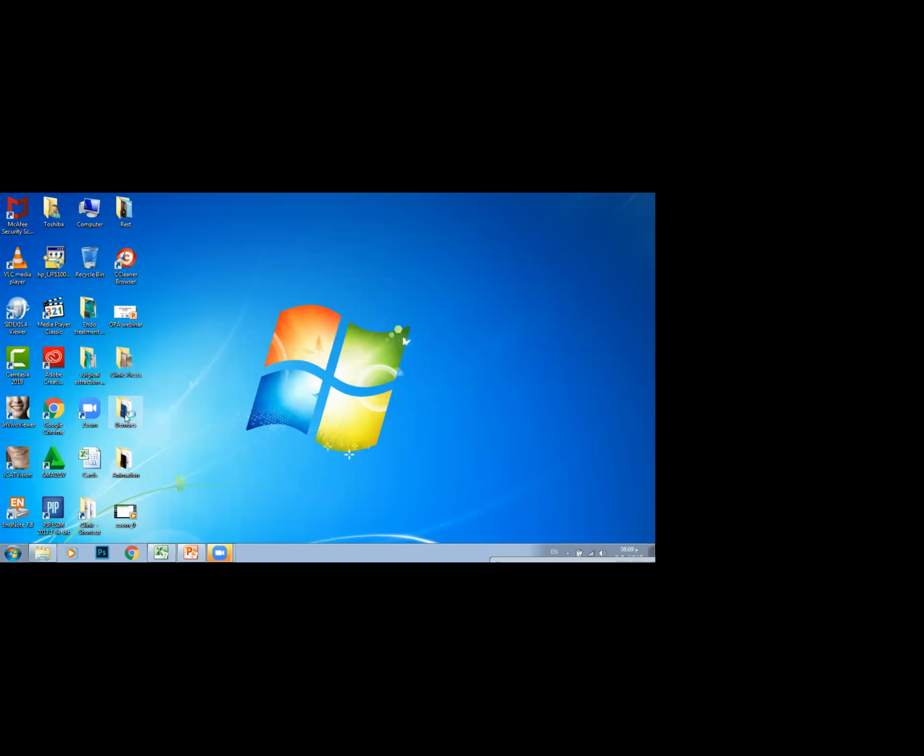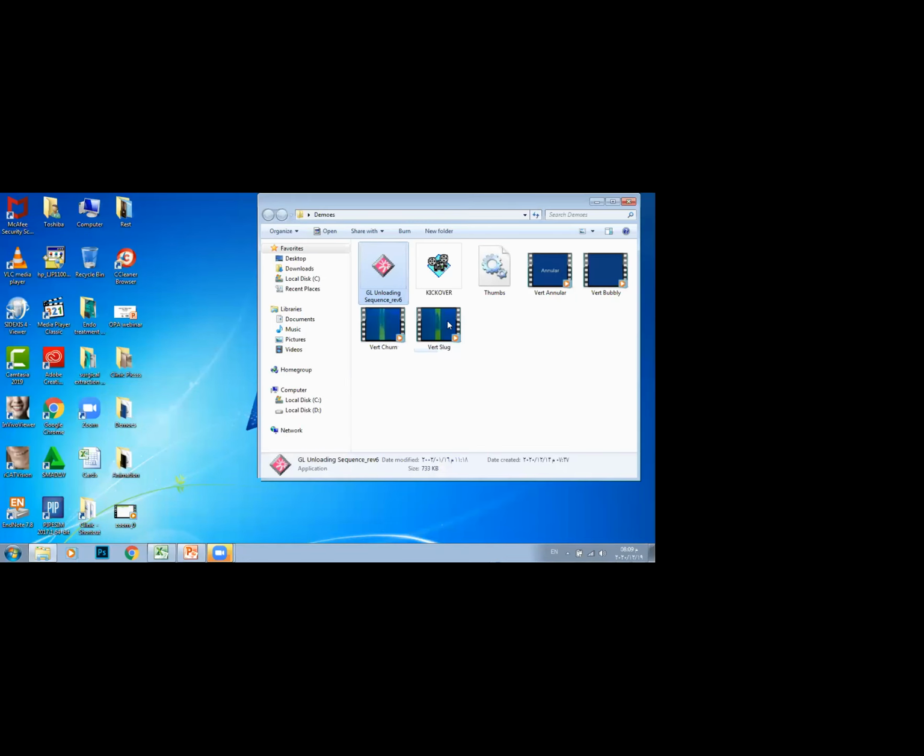So here, this is the kickover tool. I have a well. This well has a problem: I'm not injecting from the valve that I want to inject from. I'm injecting from a shallower valve. So what is the effect of injecting from a shallower valve? I'm not having the rate or the drawdown that I want.